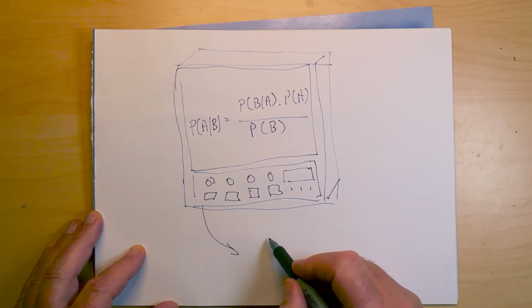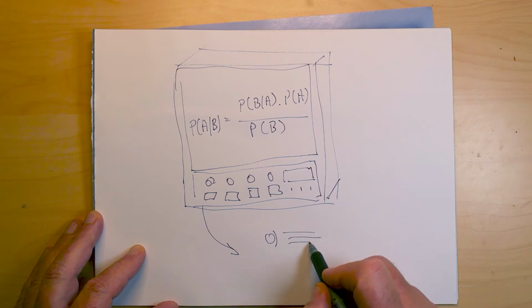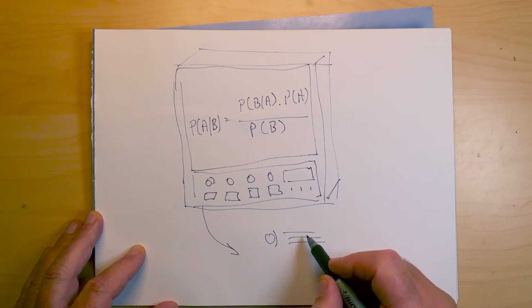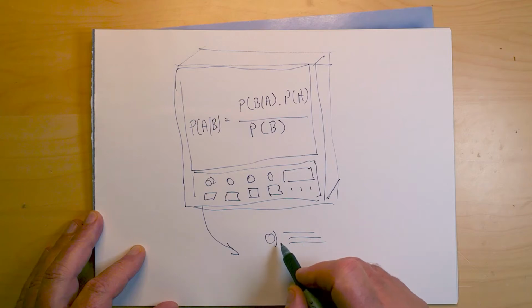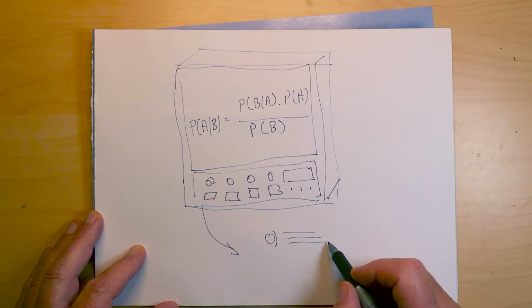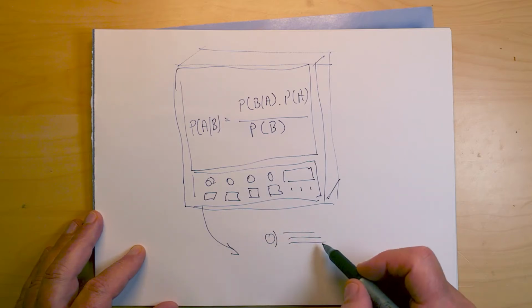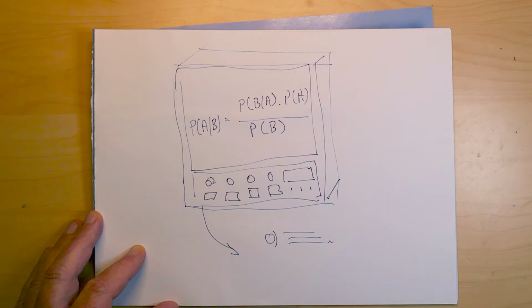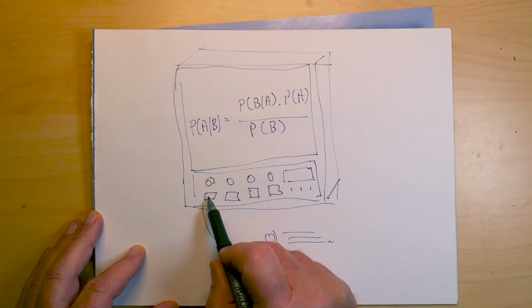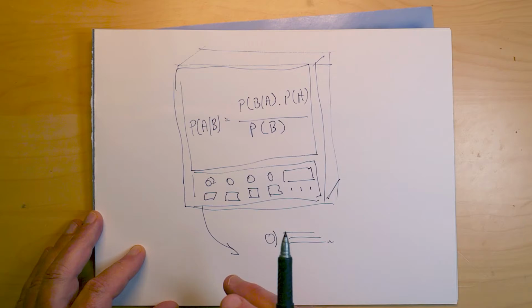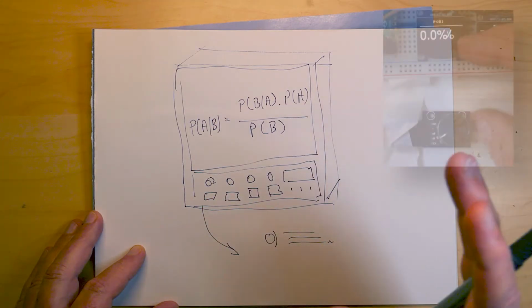So what that's going to be is a rotary input knob, and that's going to have 3 outputs. A couple of them will be used to determine the direction and the value of the rotary knob as I turn it. The third one will be on the actual knob to activate a switch, so when you push these knobs it activates this third value here, and I'll be using that to switch through which value in the number I'm adjusting, so the first value, the second value, the third value of the number.